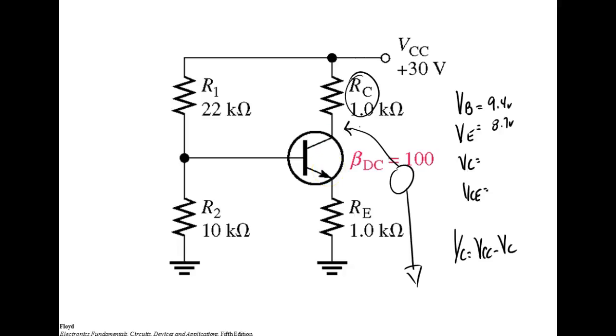But why can't you do that? Because you don't know the resistance of the transistor. But you do know the current flow there, because that's a series circuit. If I knew that voltage drop, I could add this one plus that one, but the problem is I don't know R of the transistor. I do know this R, and I do know the current flow. So if I know this R, I can calculate the current, and if I can calculate the current, I can calculate the voltage drop across that resistor. According to Kirchhoff's law, all I need to do is subtract that.